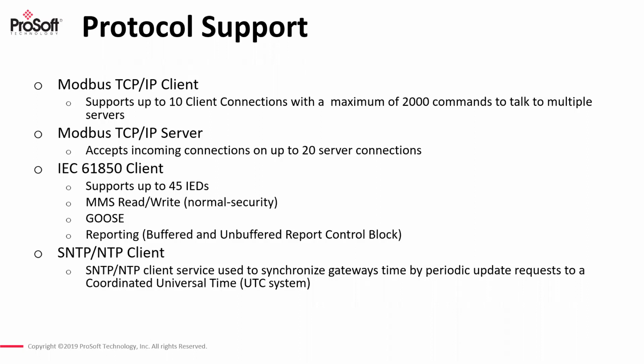Then you also have GOOSE messaging, which is high-speed burst messages sent directly from the IED devices. A lot of times those are used for communication between relays, but we also support being a GOOSE subscriber. And lastly, we've got some reporting functions implemented within the IEC 61850 standard.